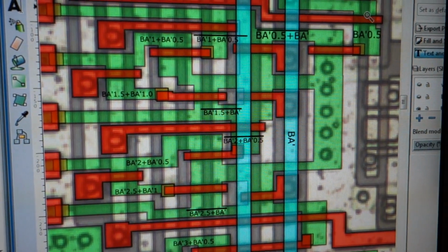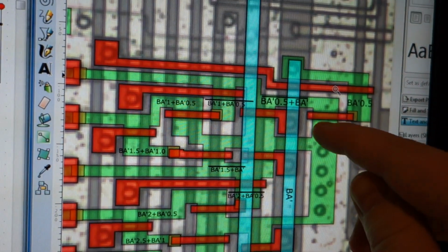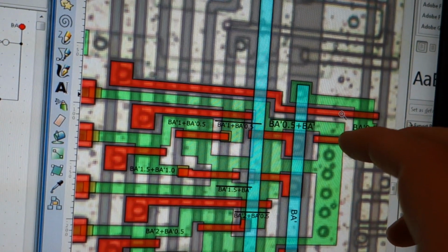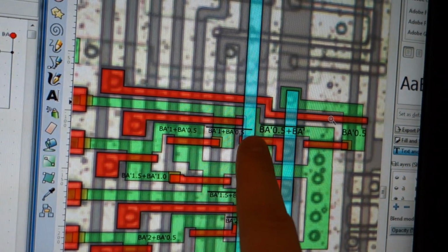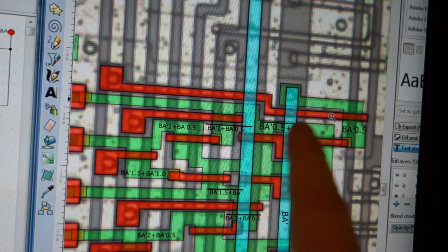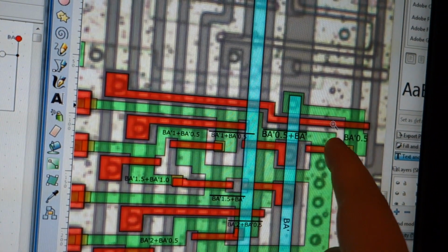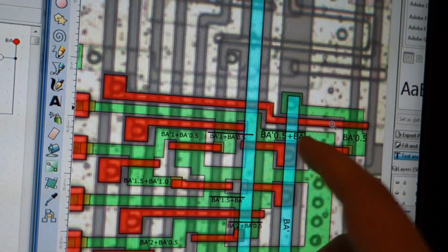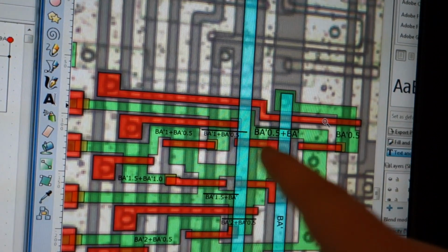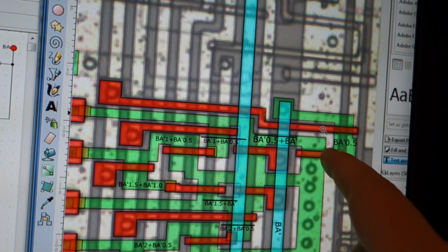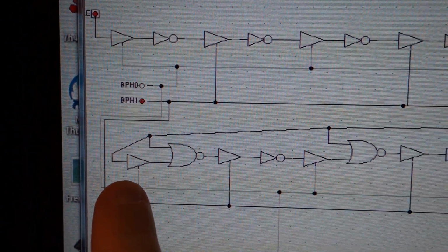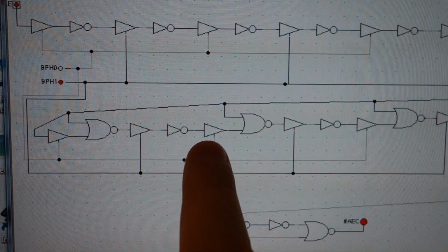You see it comes in here, and then it inverts, but it's not actually an inverter in that sense, because you also have a transistor here, so you get a wired OR, but it's not an OR, it's a NOR, because it goes to ground. So these two are the inputs to a NOR gate. That's what I have in the beginning, preceding a pass gate.